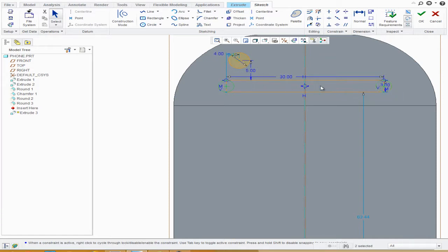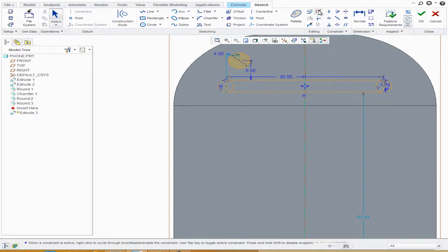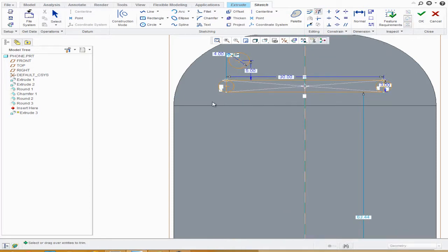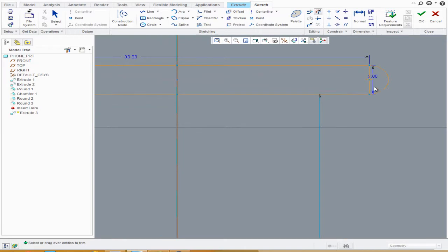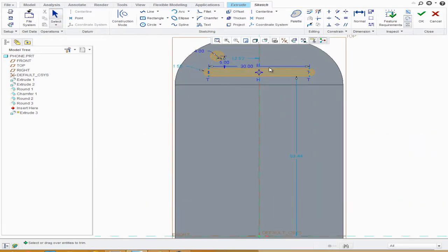This bar we've just drawn as our earpiece, where you hear the sound from the phone in, it isn't yellow, it's got issues with it. We actually need to delete these extra bits, and to do that we use the delete segment. So you just click on it on the top there, and then carefully you click the lines you want to remove. If you make a mistake, press undo. If you can't see quite what you're doing, zoom in. Now hopefully, when I press the arrow this time, you'll see that both have now coloured in.